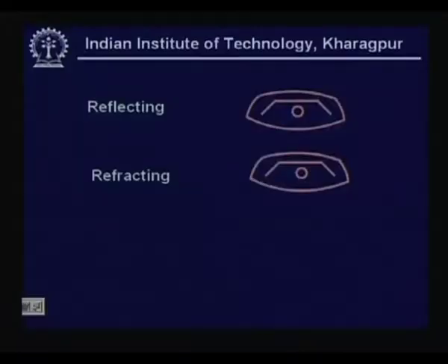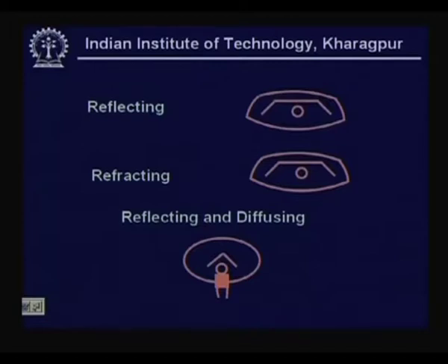This is a refracting type in the sense that the outer envelope will not be transparent glass, but an opaque thing, so that the light diffuses and comes out. This may not be suitable as a normal street light, but it is suitable for ornamental lighting of pathways in parks, when it is made at low heights where the light falls in the sight of vision and hence avoids glaring.